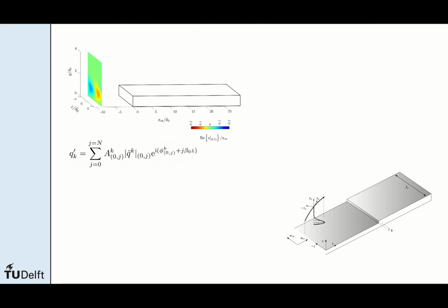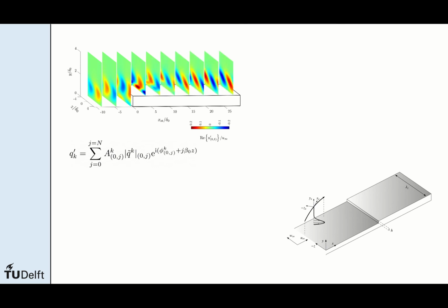From our simulations, we find that the incoming fundamental crossflow instability lifts up and passes over the step. Near-wall perturbation streaks are induced, which coexist with the primary structure, but rapidly disappear further downstream. The existence of secondary perturbation structures induced by the step is further demonstrated by analyzing the topology of the projected perturbation streamlines.